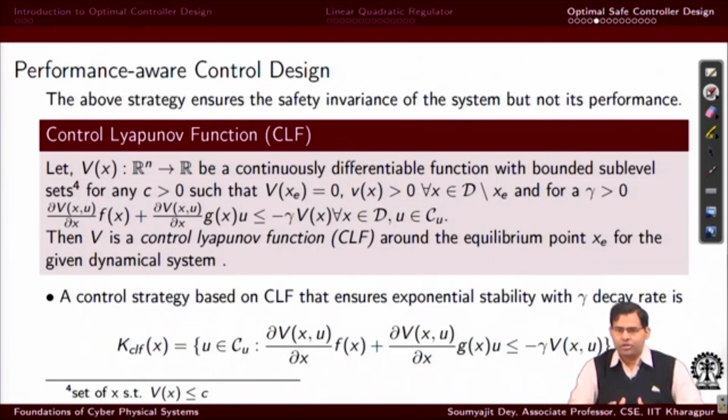It is an optimization problem, and all we are doing is adding constraints on the optimization problem so that certain performance conditions are satisfied. Here, the performance condition is that we are forcing u to be such that this equation is satisfied. If this equation is satisfied, V will decrease along the trajectory of the system following an exponential decay, which in effect gives me control on how smoothly, how fast the system approaches its equilibrium point, right. So that's the idea here.